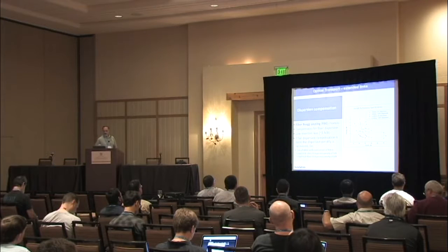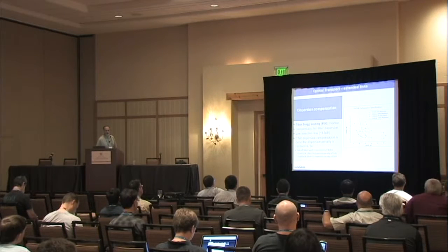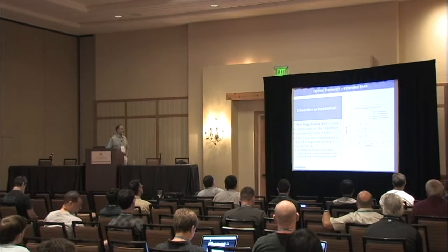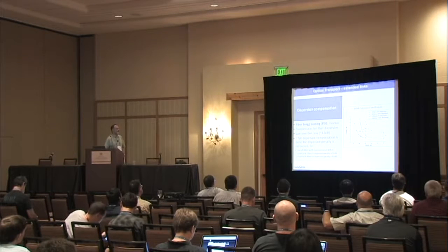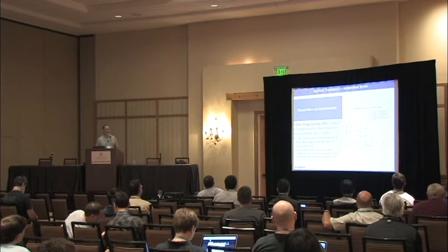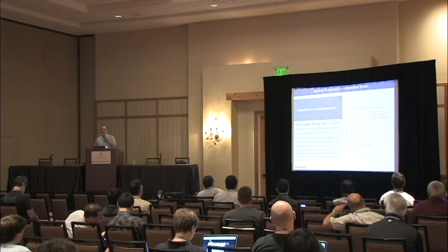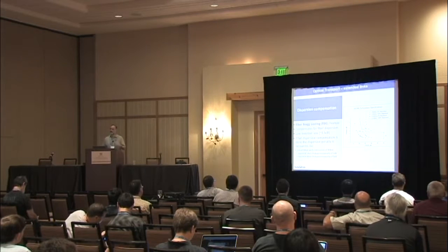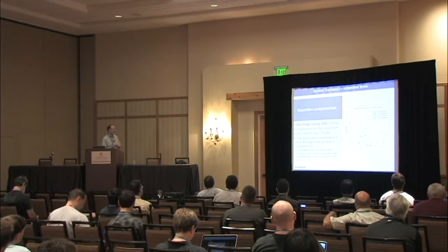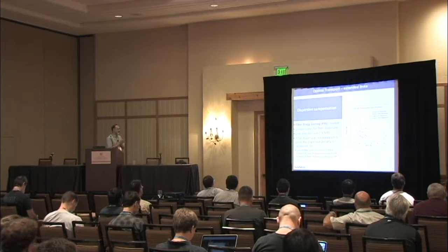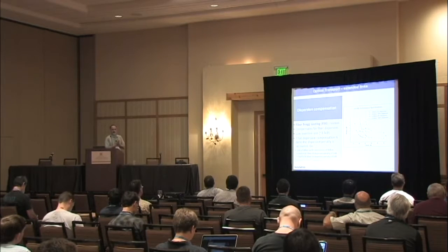So let's talk a little bit, just a tad, about dispersion compensation. Typical today is the fiber grating module. It's a small module that compensates for fiber dispersion. Very low insertion loss, that's the advantage, about 3.5 dB. And that's applicable up to 10 and maybe 40 gig, but it's a disadvantage in 100 gig installations. If full dispersion compensation is done, the dispersion penalty is recovered.